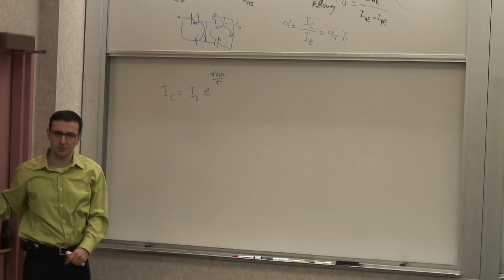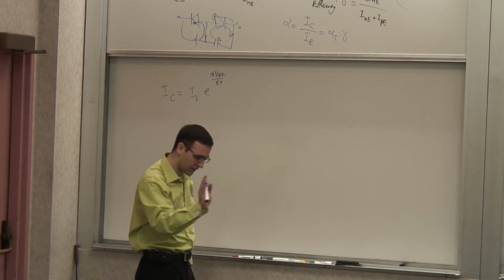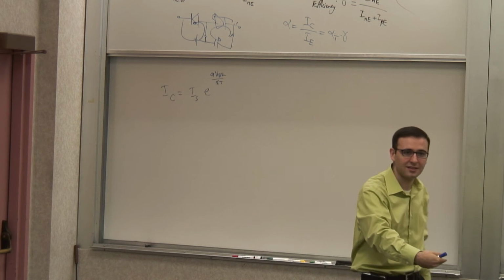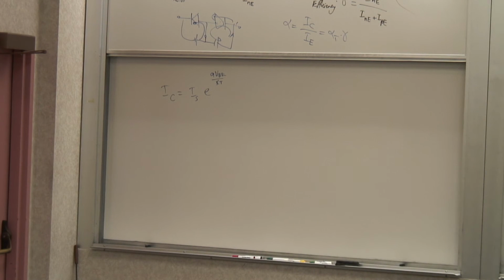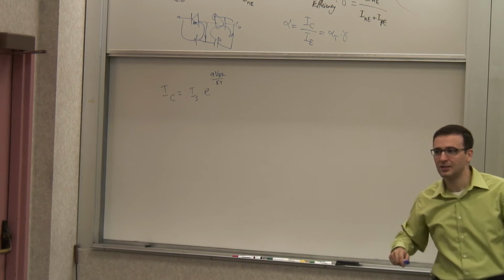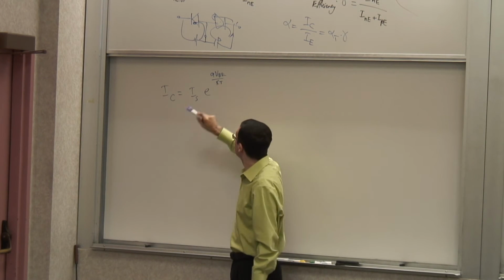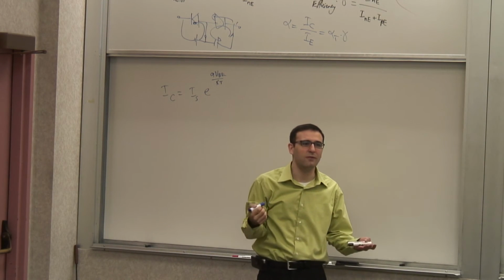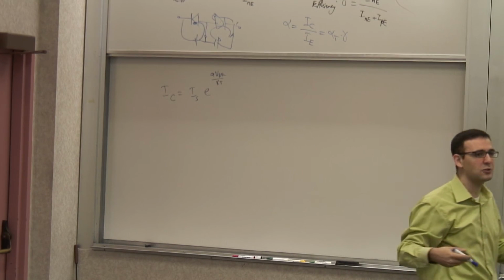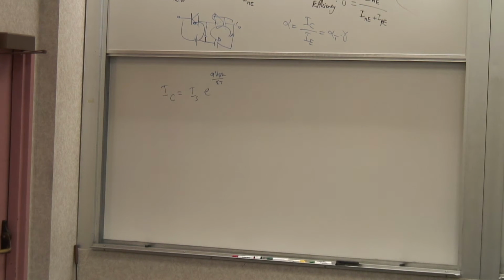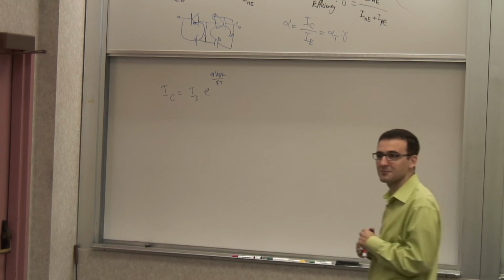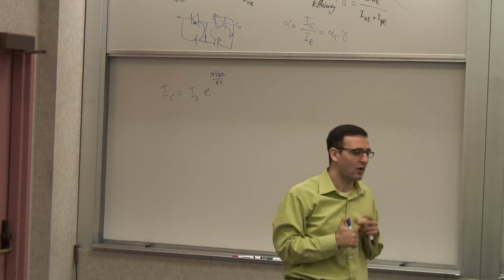As you can see, as we go along, there are many approximations we make. Some of them are very good approximations, some of them are okay approximations. This is one of the really good ones. For all practical purposes, you don't have to worry about that one, because you can calculate it. Assume a VBE of 0.6 or 0.7 volts. Remember, kT over q at room temperature is about 25 millivolts. So that's e to the 30 minus 1. Right. Okay.